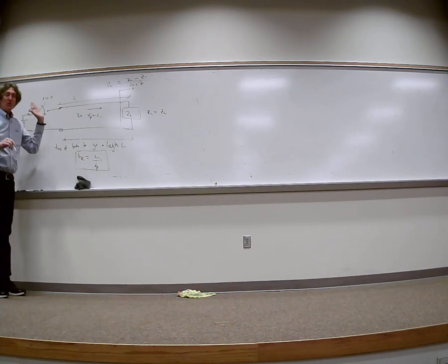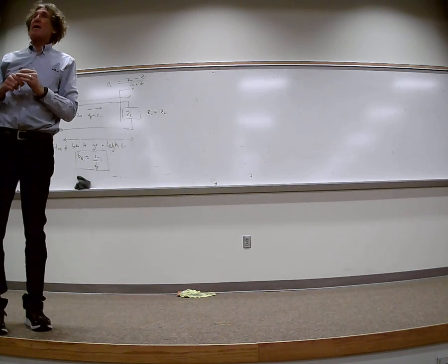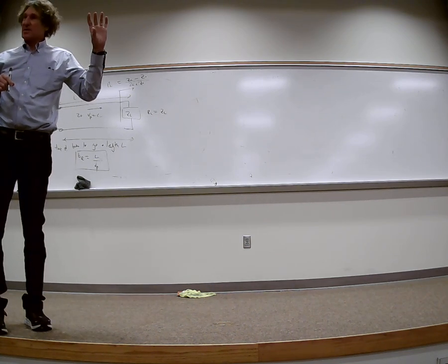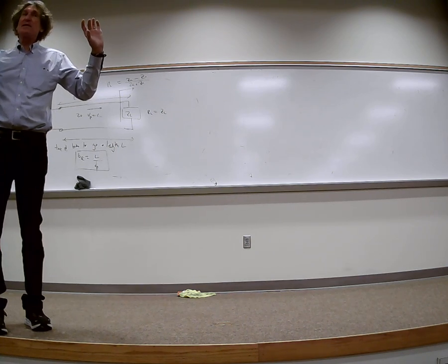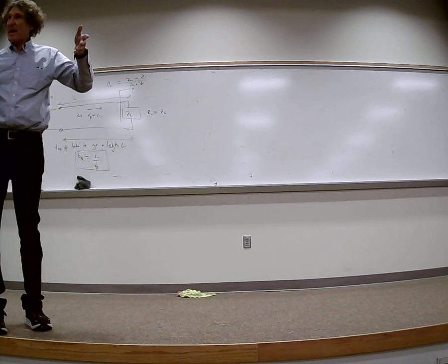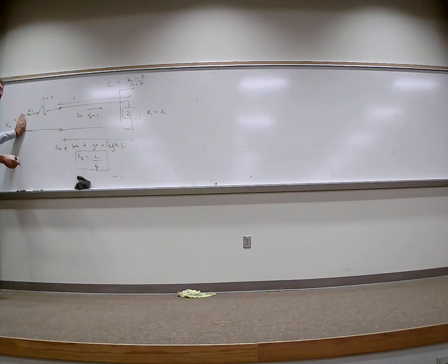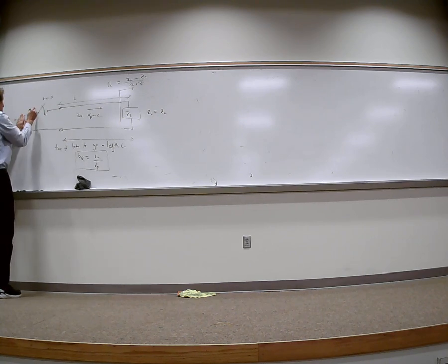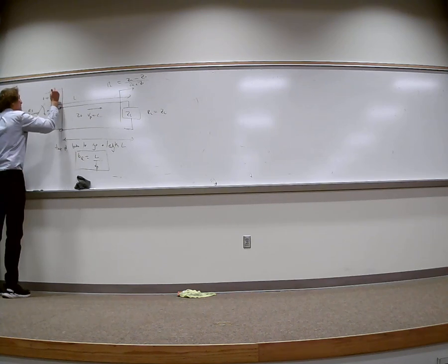hits here. Now, do y'all remember when you did Thevenin equivalent circuits? Remember how if you had an active source, a DC source, if you wanted the Thevenin equivalent resistance looking into that area of the circuit, you shorted the battery. Do y'all remember that? Here you short this battery too. And if you look this way, the actual resistance you see is RS. Do y'all follow me? So now you have a reflection coefficient here.